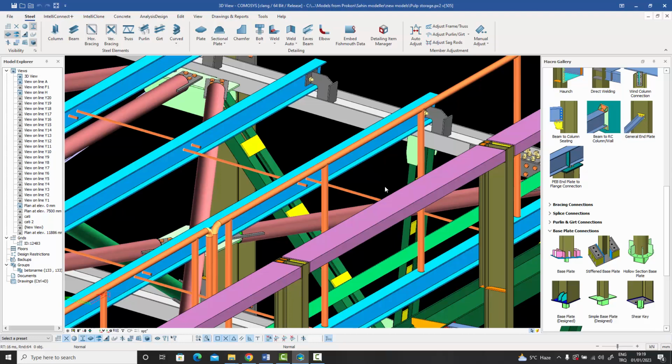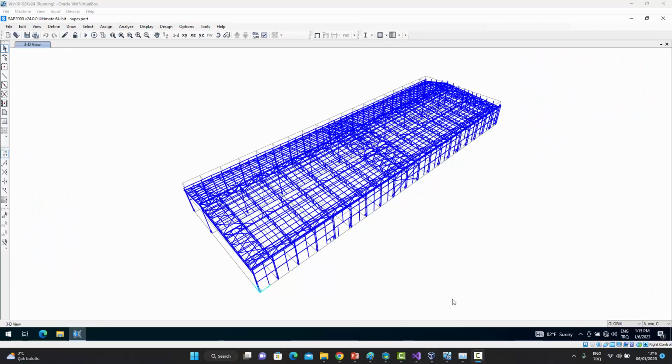And the only thing they need to do is that inside the S2K file, there is a reference to the PRO file, which is the section parameters. And there's a path, a local path. So this local path is basically dependent on your machine. So if you're giving it to someone else to use, then you need to change the path of the PRO file given in the S2K. This is a simple find and replace command. You just look for all the instances where the PRO file has been mentioned, and then quickly find and replace with the new path, and you will be able to use it.